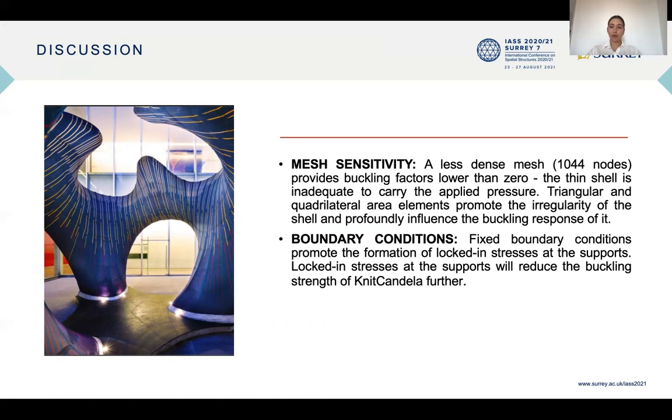Another parameter that was found to influence the buckling performance of the shell under investigation is the boundary conditions. Fixed boundary conditions promote the formation of locked-in stresses at the supports. Locked-in stresses at the supports have the ability to reduce the buckling strength of KnitCandela further.